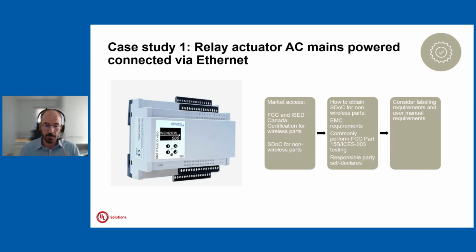Industry Canada may also have labeling requirements, and both FCC and Industry Canada will have user manual statements that are mandatory to be present in the user manual. Something also to be mentioned here is that for Canada, you will need to consider writing these statements in French too, because it is mandatory for Canada to have both English and French versions.